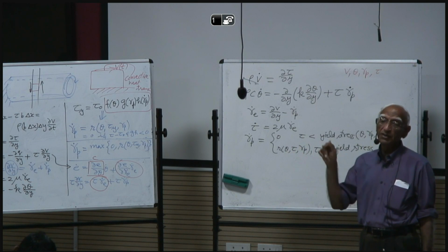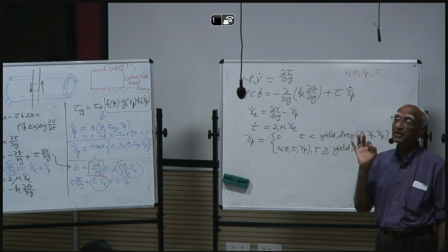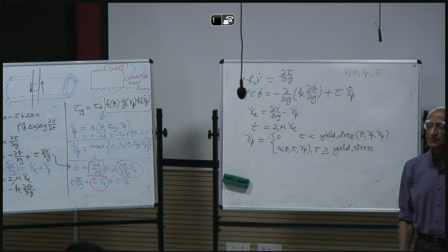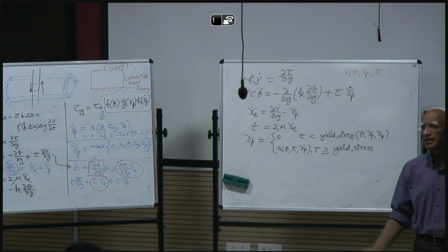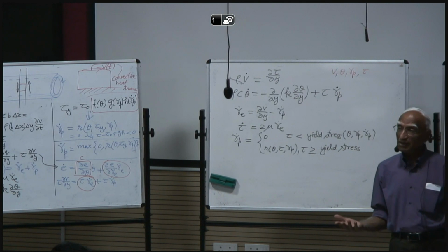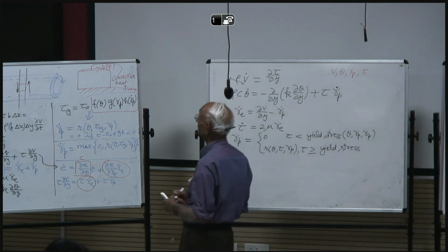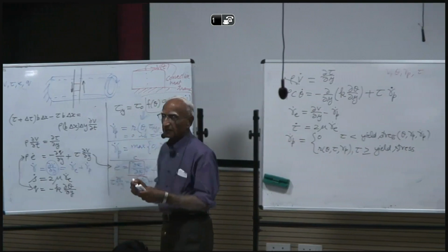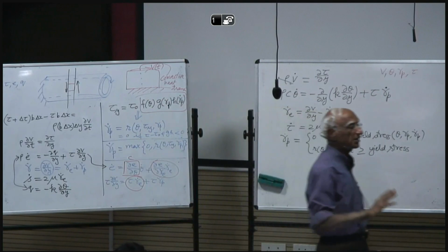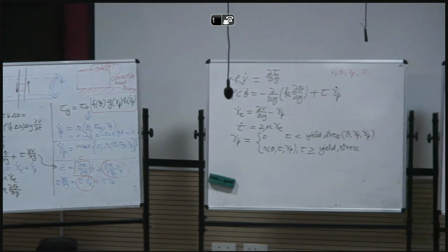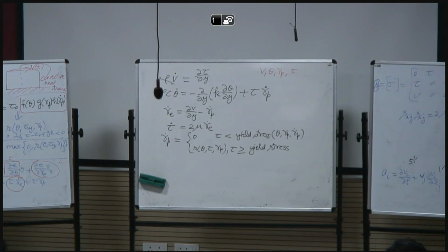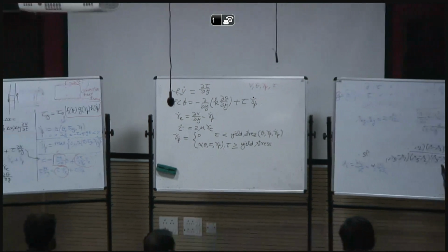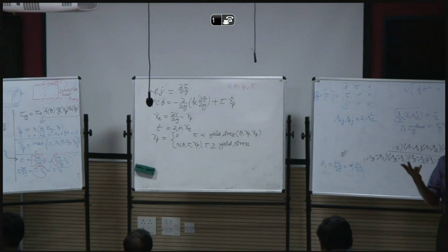Depending upon where you introduce the defect, and how big a defect you introduce, the instability or the shear band will occur at different times. You can introduce multiple defects, say a defect here, here, here, and here, and then see how these defects interact with each other. There is no guarantee that if you have introduced 4 defects, you will get 4 shear bands. You may get only 1, or you may get 2.